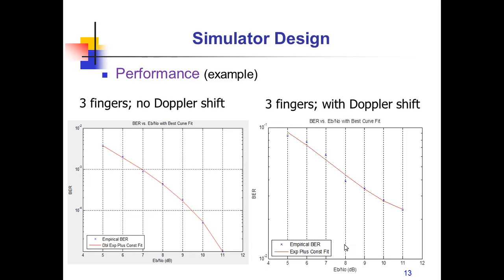We can see that the BER is dropping quickly as the SNR increases. In the second plot, the channel includes Doppler shift. The Doppler shift frequency is set to 10 Hz. As we can see in the plot, the bit error rate is significantly larger than the previous one.